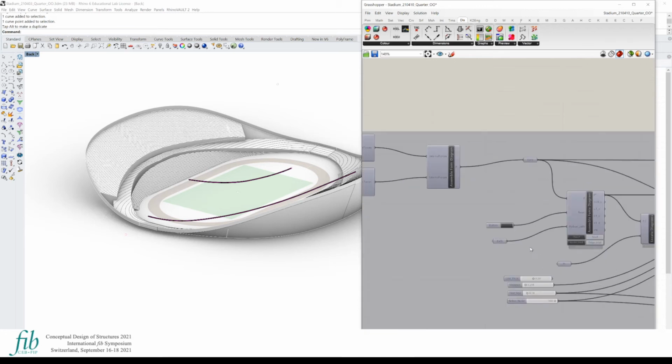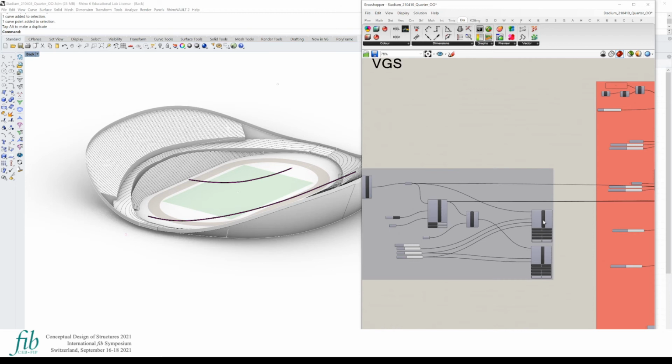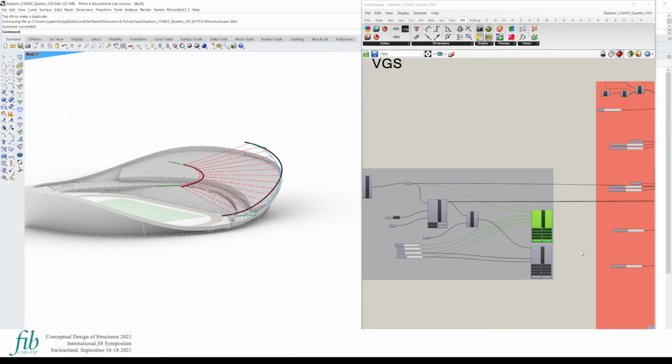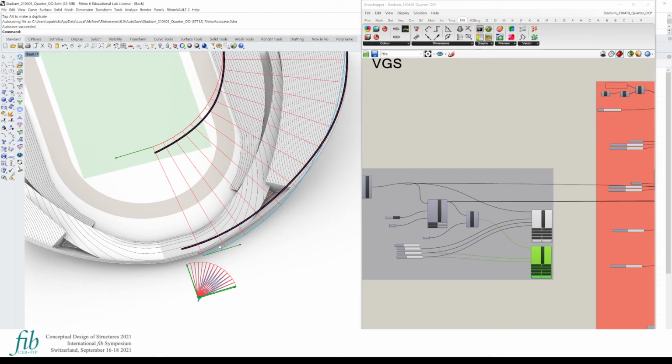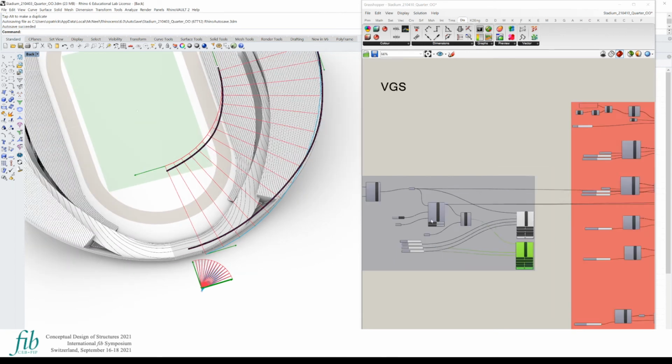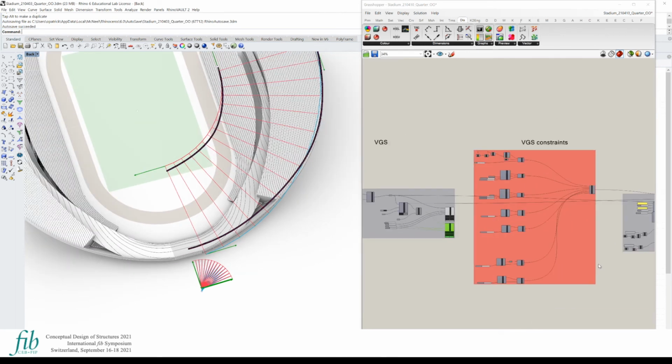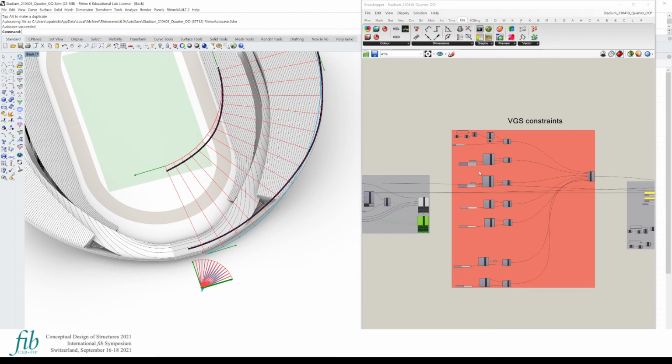Then we can press the button to assemble the force diagram. You see it here. After a short moment, you see the form diagram that corresponds to the form diagram of the CEM. But you now also see the force diagram, which you see here at the bottom of the stadium, visualized. In the next step, we can start formulating constraints in order to transform this equilibrium state.